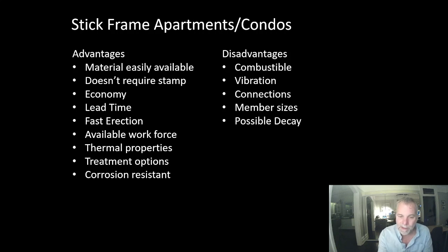Also, materials that are outside of the building envelope have a different design life. So we're building a building for a 100-year life. If we have an exterior deck, we just have to assume that it's got about a 20-year life, a replacement life. So we don't have the same longevity in all of our materials, or of all our elements within the building.